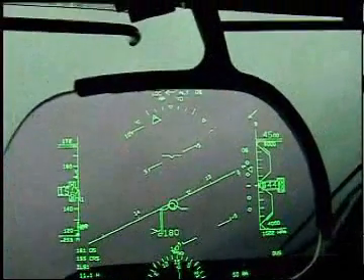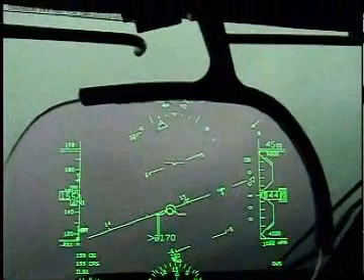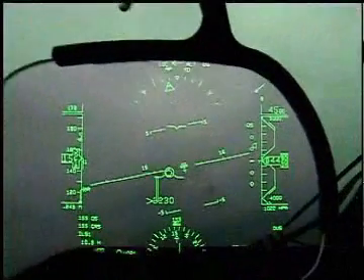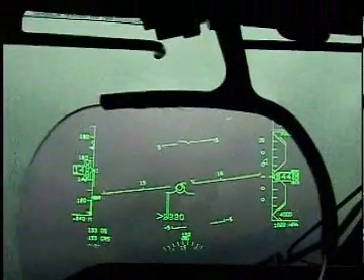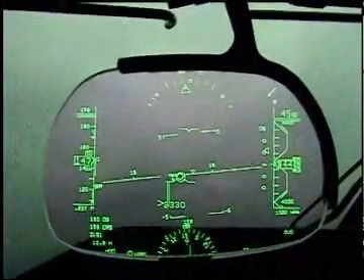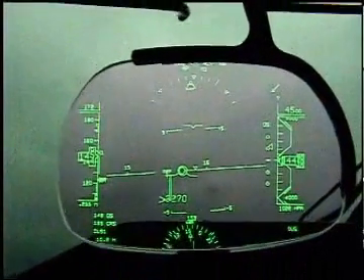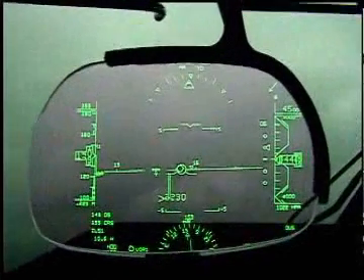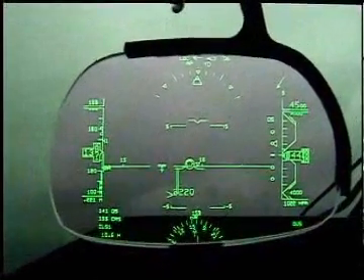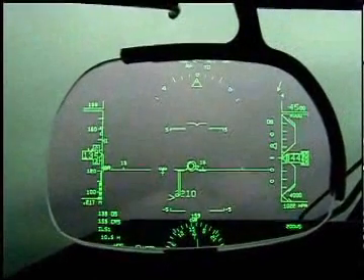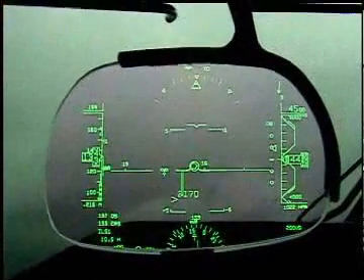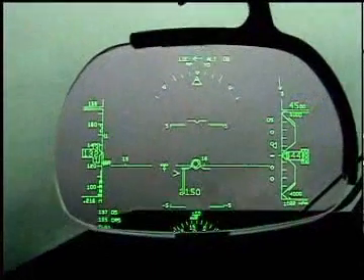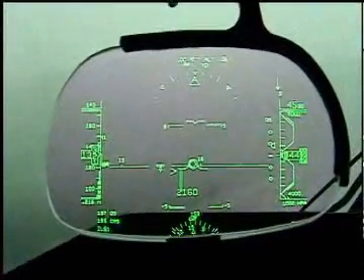The current assigned heading is indicated by the digital selected heading value and the heading bugs on the horizon and HSI. The ILS course is also indicated by the digital selected course value and the course pointer on the HSI and below the horizon line. The aircraft is level at the determined altitude, intercepting from below the glide slope. The aircraft is out from the ILS DME station, and the aircraft is decelerating slightly to obtain the target airspeed.